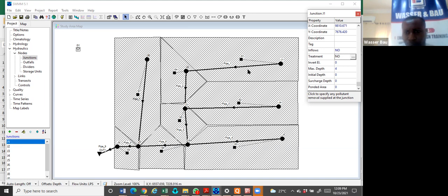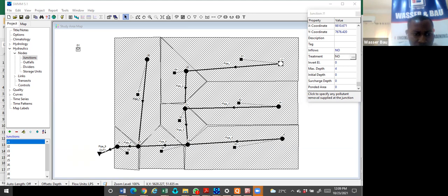Now let me ask you something, gentlemen. The length of this pipe is 500 meters. If this place is, say, let's use 100 as benchmark, and you are given that the slope is 0.5%, what would this place be? It would be 0.5%, which is 0.005, multiplied by the length. That will give you the value of this place. It will be complicated for some of us, but we're all engineers. So let me use calculator.